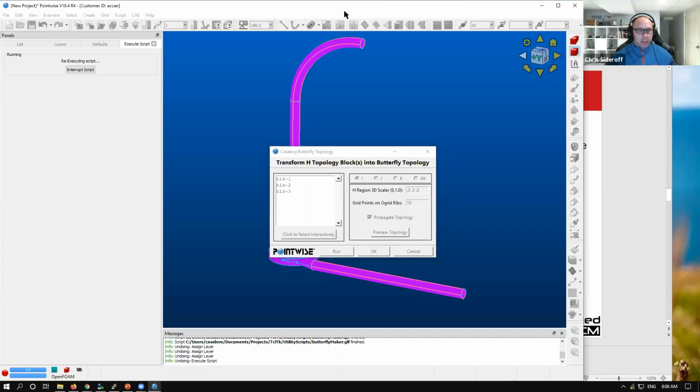So the last step, when this finishes up, is that we're going to mate up the structured mesh and select values. I'm going to have to get from the clicker here. So I'm just selecting the layer, and putting this in there, outlet mesh. There we go. So the last step, going back to Ivan's questions from before, is that I'm going to pack the mesh near the wall in the structured mesh.